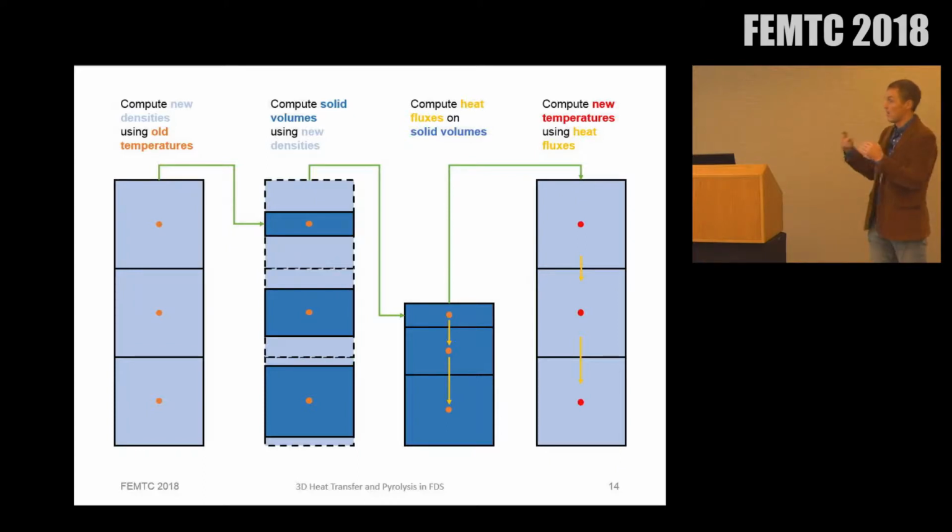Once we have these little vectors that represent the heat flux, a cool property of these finite volume methods is that you can simply take these and move back over to your original Eulerian grid, and things are still conservative. You can conserve energy and mass within this cell; you just need to know what the flux is.